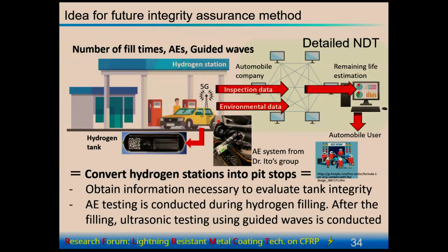During the hydrogen filling, we do acoustic emission testing, and also use ultrasonic guided waves, and do some simple NDT. So we say, convert hydrogen stations into Formula One pit stops. During the filling, not only do we fill the hydrogen, but we do the inspections.